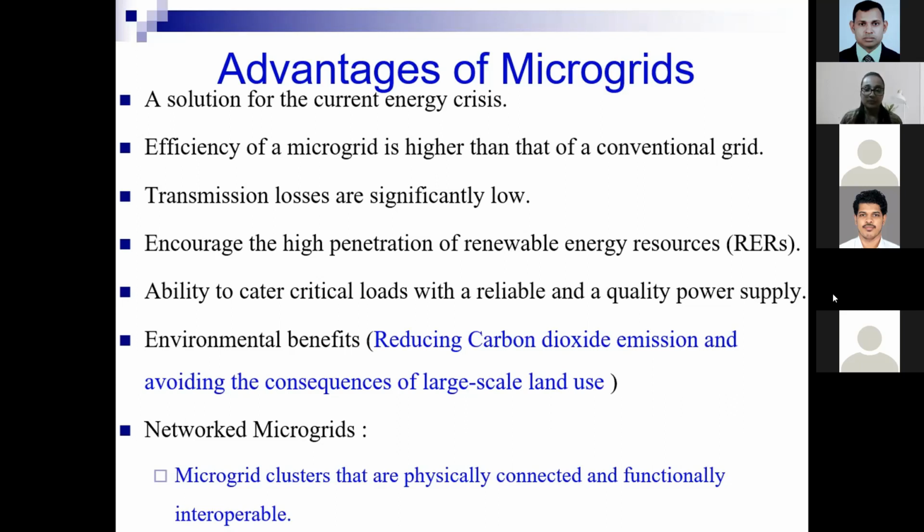As a novel approach, as Professor Dhyanga mentioned before, the closely located island microgrids can be networked as microgrid clusters. Let me explain what is a network microgrid. It is made of microgrid clusters that are physically connected and functionally interoperable. And the networking of microgrids allows these islanded microgrids to share their extra generation resource capacities among themselves.